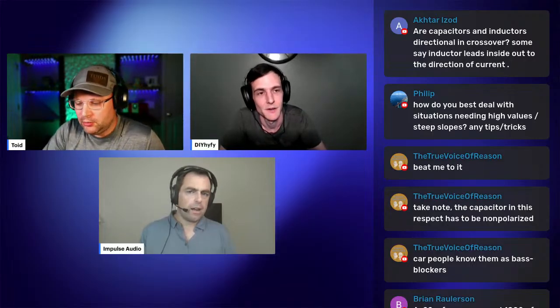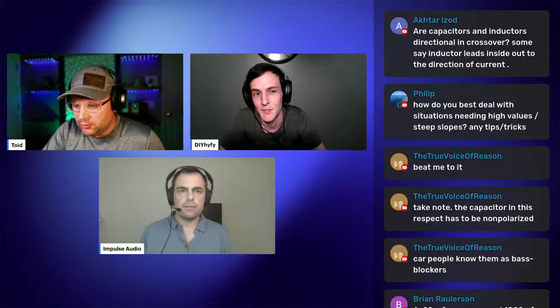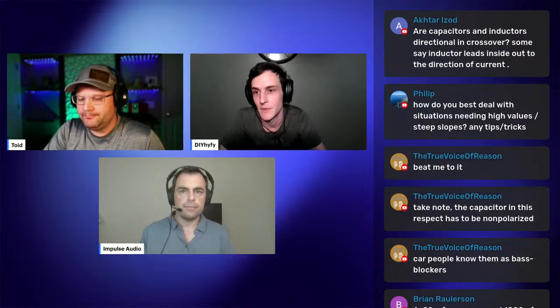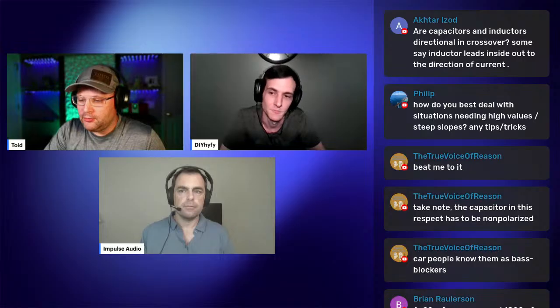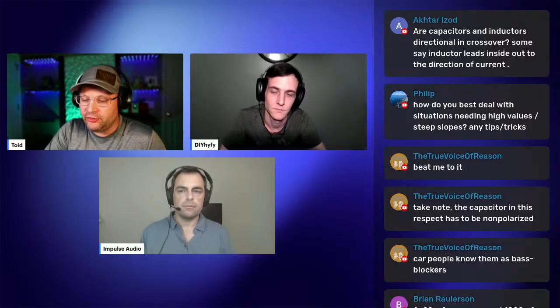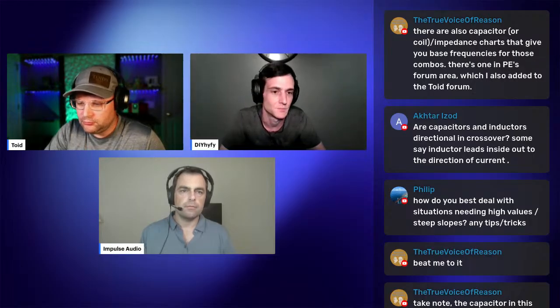Someone asks, are capacitors and inductors directional? I assume they mean polarized. If they mean directional in that sense, no, you should be using non-polarized components. Be careful because there are polarized capacitors, but if you're using them for a crossover, you should be using non-polarized. If you've got a crossover component, you can assume it can be wired up in either orientation. There should not be a technical positive or negative side of that component.